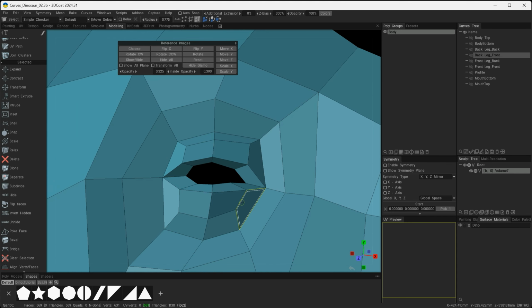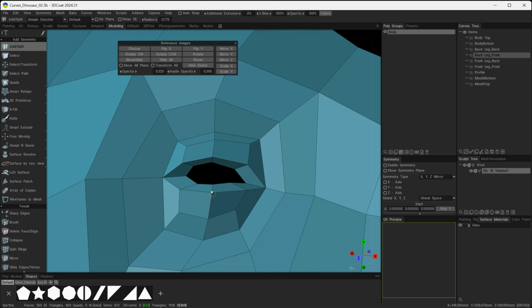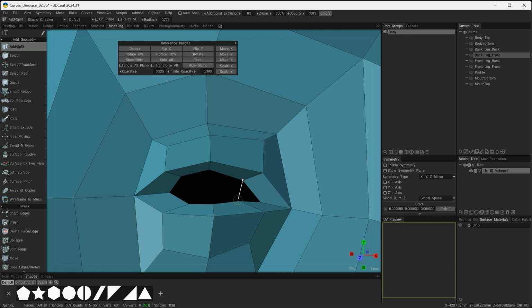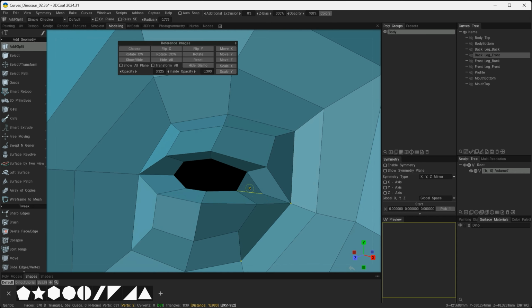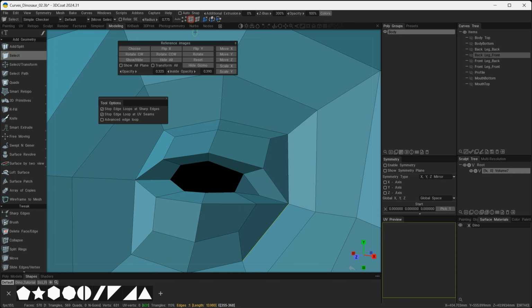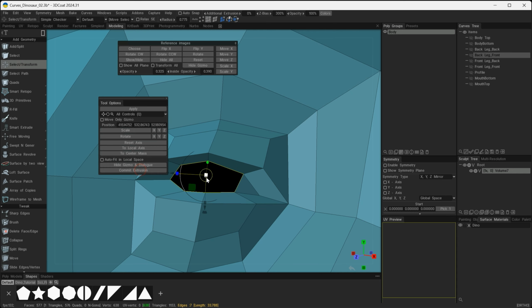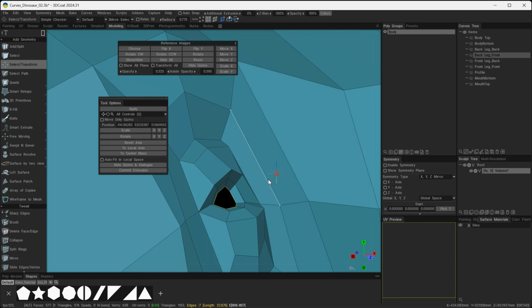So with the eye blocked out, I'll just close this open edge here by creating some extra geometry inside. I'd like to join these 2 points here. And this will be the corner of the eye here. And then I'm going to select these edges around. And I'll just do the same thing where I commit an extrusion, pull these inwards and push them back into the socket a little bit further that way.